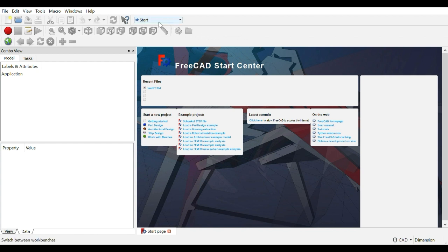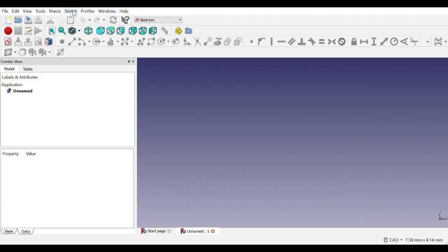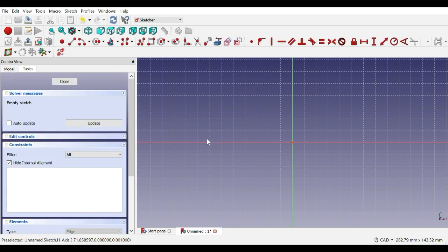So let's get started. We start with a sketch. This won't show up on your screen, but I'm selecting the Sketcher. I'm using Windows recording and it doesn't show the pull down menu. Okay, so now Sketcher, File, New. You have to do that. Then you also have to hit Create Sketch. Sketch, Create Sketch. And the XY plane is for CNC machines. Click OK.